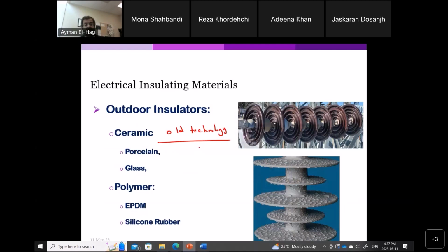One of the major issues with those insulators is their pollution performance. Once they are wetted, there is wetting on the surface of these materials, there is a leakage current, and there is a flashover. How can we solve this issue? By washing the insulators. Now, sometimes, especially in highly humid and highly polluted areas, that is not an economically good solution because the cost becomes huge. In certain areas of the world you need to do the washing every 6 weeks, sometimes every 2 months. And imagine that you have those transmission lines for hundreds of kilometers. That is a lot of cost.